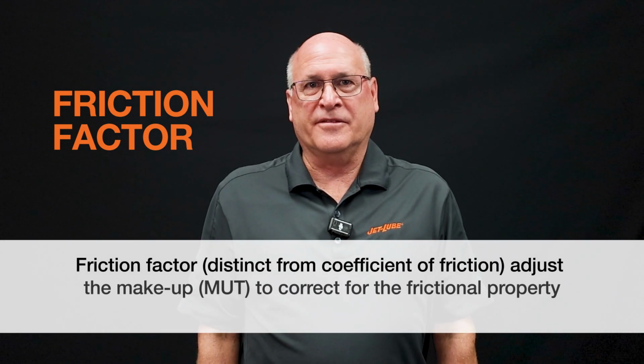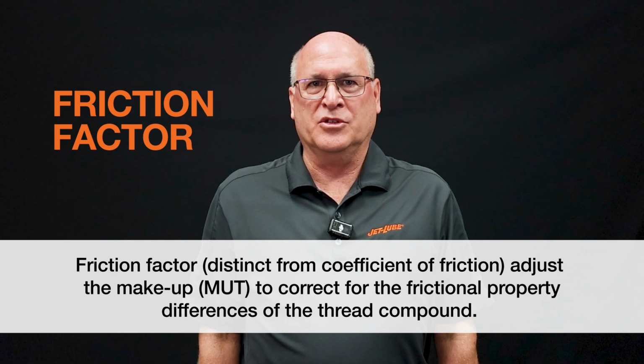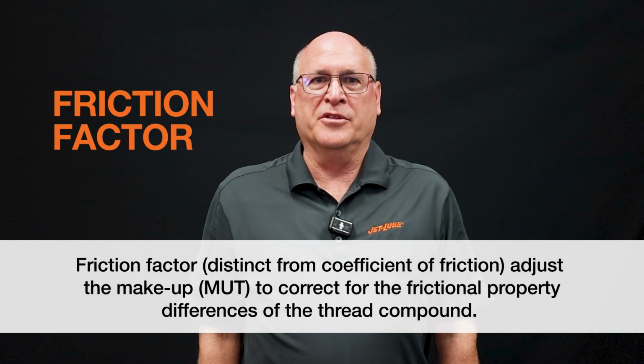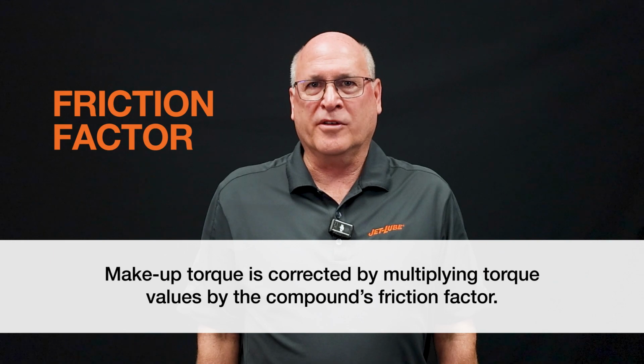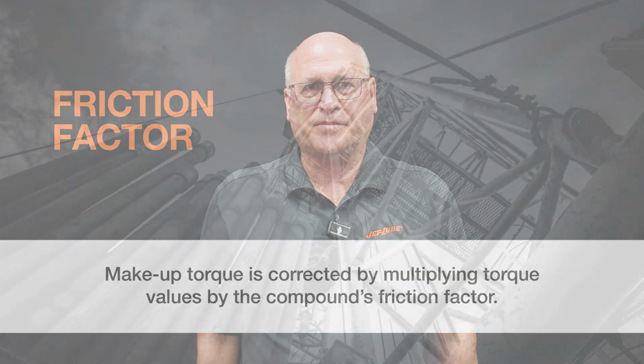Friction factor. Friction factor, distinct from coefficient of friction, adjusts the makeup torque, MUT, to correct for frictional property differences in the thread compound. Makeup torque is corrected by multiplying torque values by the compound friction factor.